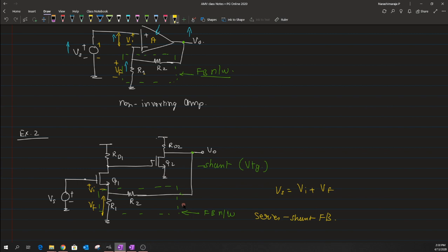And again, in order to check whether the feedback network is actually a negative feedback, one could again start with the discussion of Vs when you raise it. What happens is that the current through this Q1 will also rise up. Okay, and when the current rises, the drain potential, which I'll write as VD1, will start dropping, just because VD1 is defined as VDD minus ID1 times RD1.